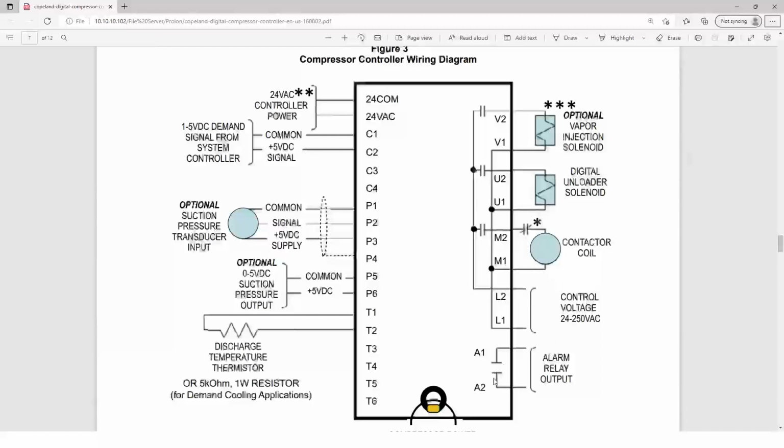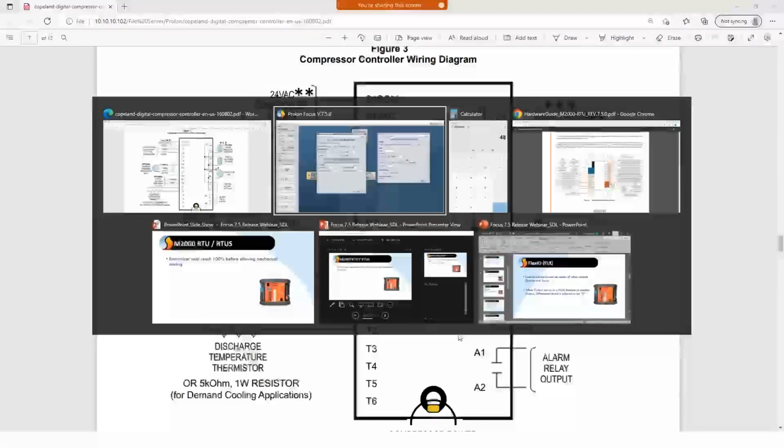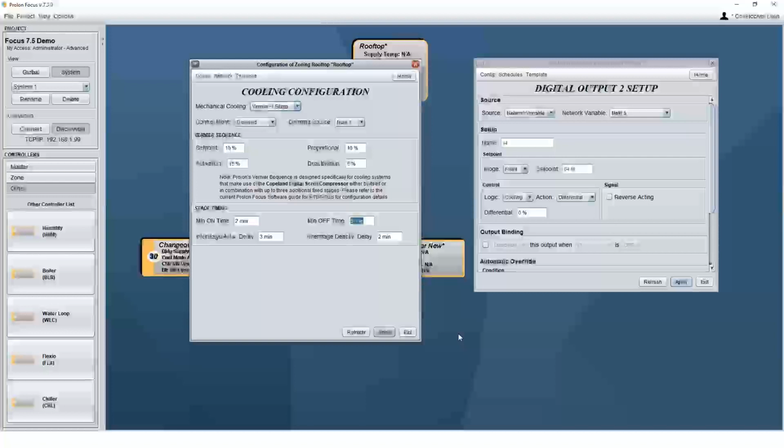Technically, this controller could operate the compressor from start up through its whole modulation back down to stop, shutting the motor off of that 1 to 5 volt signal that is being provided. But what we see happening with manufacturers is that they are putting a second enable relay. It still wants a Y1 command to allow the motor to start, in addition to the 1 to 5 volt signal to modulate the compressor.